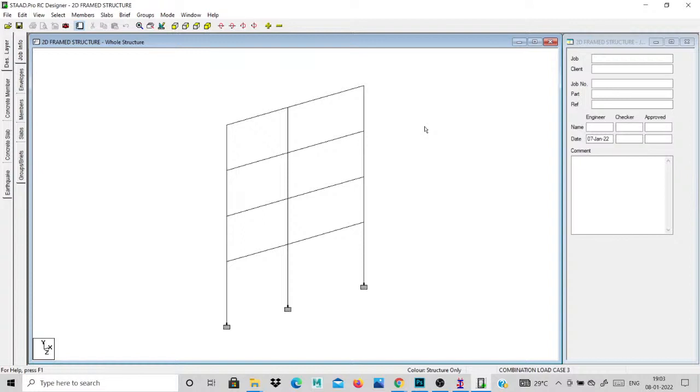Okay, how to design your beam in advanced RC design. These are the five procedures to be followed, five steps. One is you create an envelope, second is the member, third is the group and brief, and finally the fifth one is analyze. This is the five-step procedure to design your advanced RC elements for beams and columns.